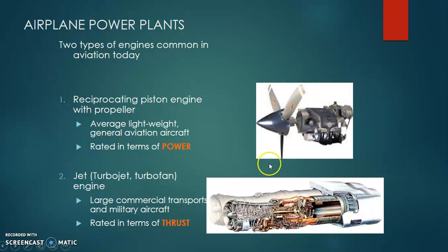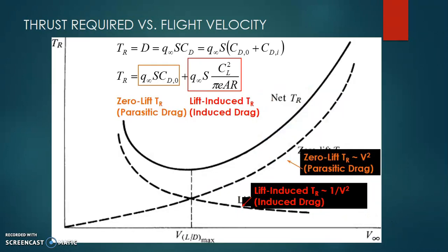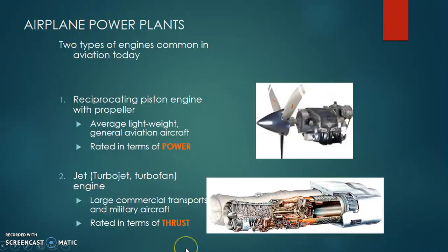engines are not proven to be extremely rugged, and the failure modes in structures coupling with aerodynamics go up substantially compared to the closed and simple intake based turbofan or turbojet engines. All military engines will have a simple turbojet or turbofan because of the extreme demand of variation of thrust, as we saw here with time, because of these maneuvers.